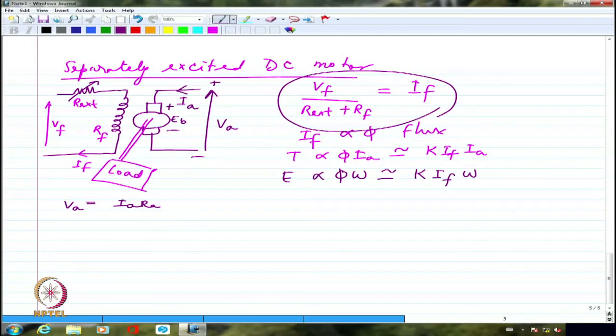You think about it. You have basically a conductor sitting inside the armature. I have applied a voltage, right? When I have applied a voltage, it is going to carry a current, in all probability an enormously large current, unless I limit it. So it is going to carry a large current and it is going to generate a torque. Because of the torque, it is going to start moving. When it is moving, the same conductor, which is actually sitting in a magnetic field and it is moving, will have an induced EMF. And that induced EMF we call the back EMF or counter EMF. That counter EMF cannot be dominating over the applied voltage. If it is dominating over the applied voltage, the entire action of the machine is killed. It's not going to have any current, right? So necessarily that voltage is slightly subdued or less than whatever is the applied voltage. So that is less by what amount? That will be less by IA RA.